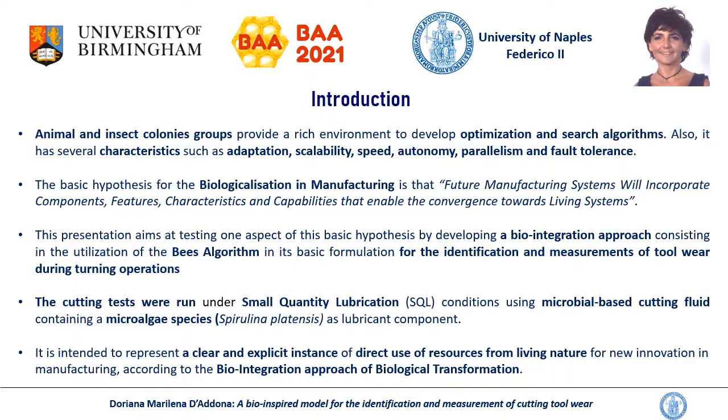The cutting tests were run under small quantity lubrication conditions using microbial-based cutting fluid containing a microalgae species, in particular Spirulina platensis, as lubricant components. It is intended to represent a clear and explicit instance of direct use of resources from living nature for new innovation in manufacturing, according to the biointegration approach of biological transformation.